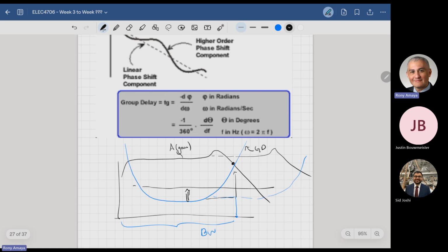That the actual gain transfer function is also serving a third purpose, which is noise cancellation. So if I open up the bandwidth, I'm passing more noise. And that noise will show at the output, but can also always be input referred. It would actually now start to limit the minimum detectable noise that you can work with, which is your thermal noise level in your system, right? So you can see how complicated this thing is.